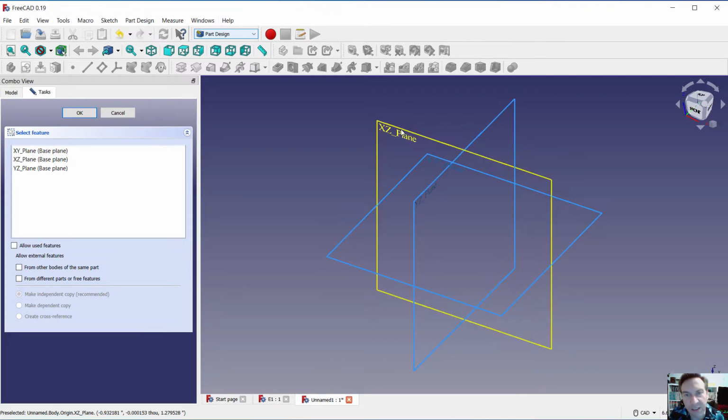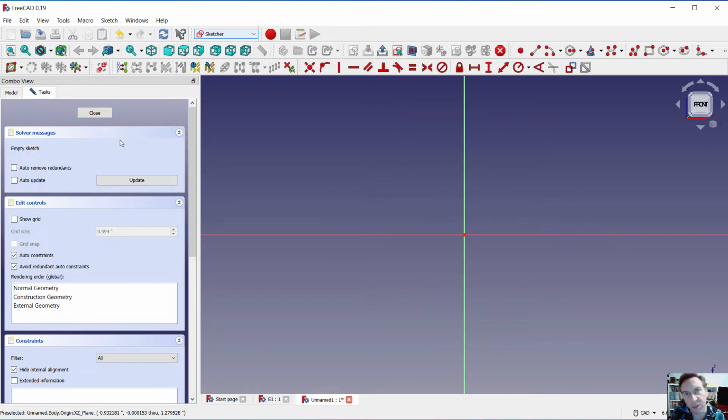You'll see this is a plane-based model, much like Inventor, SolidWorks, Creo. Let's go ahead and select the XZ plane. I always sketch usually on the front plane, that's the XZ plane. The top plane comes in handy as well, the XY. Let's select the XZ, and then over here, hit OK. And it will bring us normal to that. Now you see here we have the ability to use this to rotate and do different things. We're going to touch upon that in a little bit.